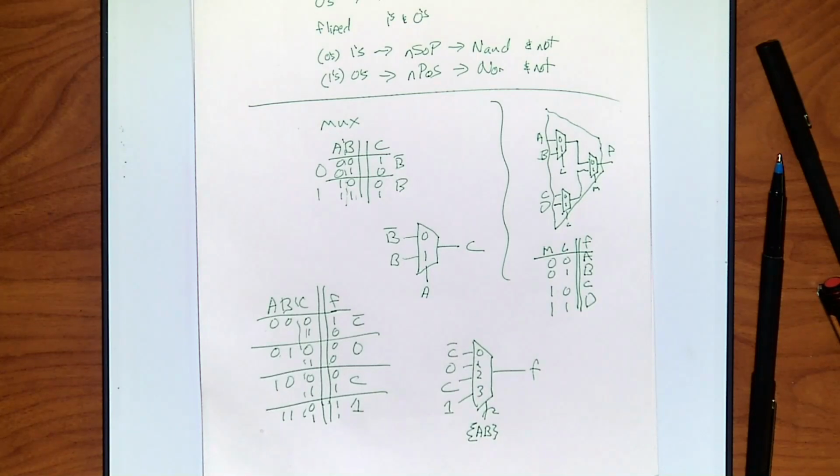I submit to you mux design is one of the coolest design techniques that's out there. And AB is an address line because it's 2 bits. To control 4 inputs to a mux, you need 2 wires. So I'm just specifying the order I put them in. I put them in curly braces, which is the sequencing command inside of Verilog. I'm just saying, treat this as my 2-bit control wires coming in. So I needed the most significant and the least significant bit.